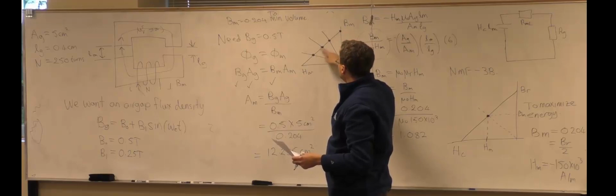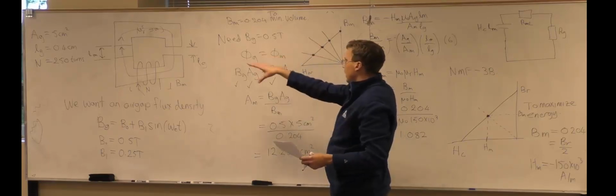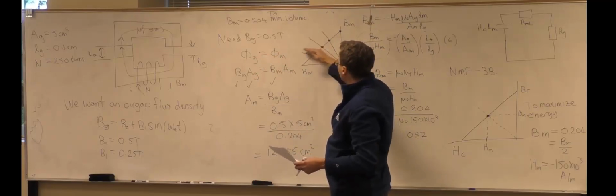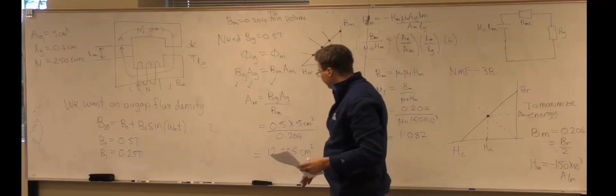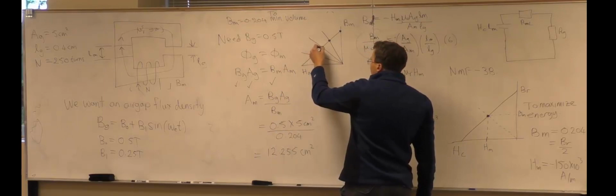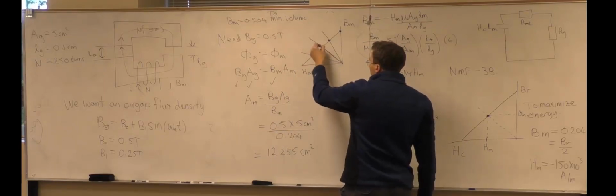We can choose some of these regions down here, and that will govern the gradient of the load line that we get, and we can select our geometry to have that particular load line gradient. If we get it right in the middle, we'll have the smallest magnet.